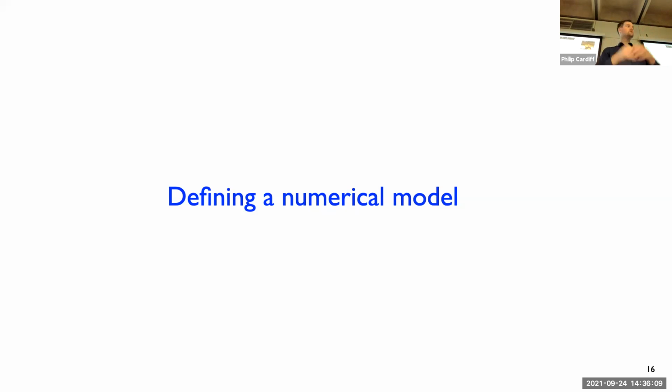And once you define that simplification, perfect, straight, clean holes, Hooke's law with parameters, then it's up to a finite element method to solve that. And then the finite element method doesn't do that exactly. It also has errors, for example, to do with the mesh. Those are numerical errors. They're unrelated to your assumptions about the real life problem. It's just related to computer methods' inability to solve it exactly.